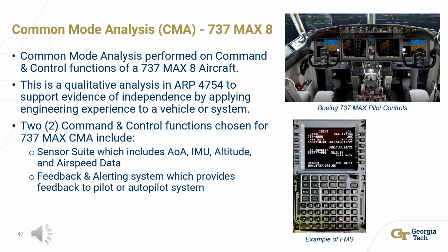Now we move on to the Common Mode Analysis, or CMA. In this CMA, we'll be looking at the command and control system for a 737 MAX 8 aircraft. This is a qualitative analysis as listed in ARP 4754, using engineering experience to support independence of systems or a vehicle. In this case, we will select two command and control functions seen on a 737 MAX aircraft. These are the sensor suite and the feedback and alerting system.